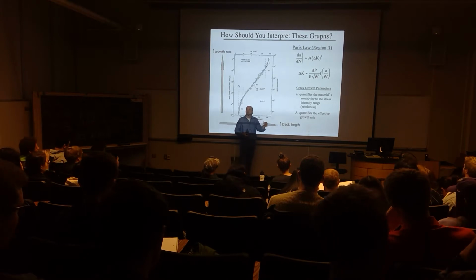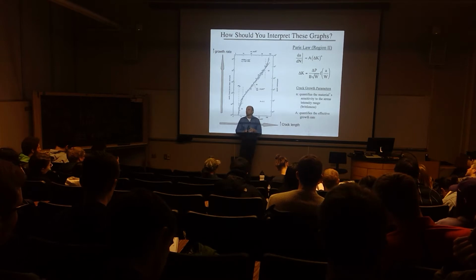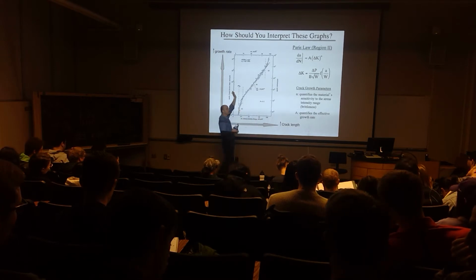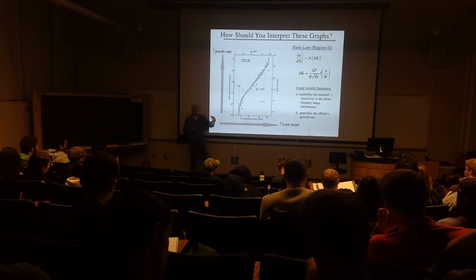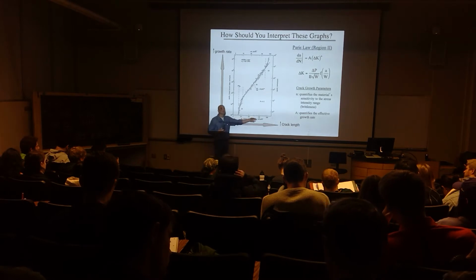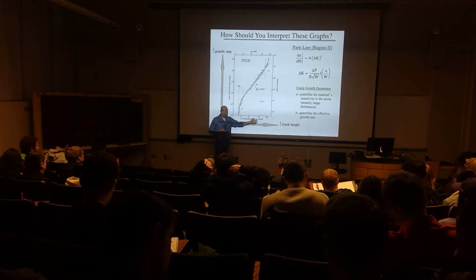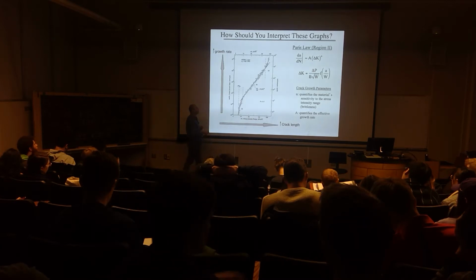As the crack gets longer, it causes an acceleration of the rate at which the crack grows, because the stress intensity is getting bigger. There's more driving force, not because of the surface conditions; it's happening because the crack is increasing, which increases the magnitude of stress intensity. And I'll point out why that's important in a little bit.